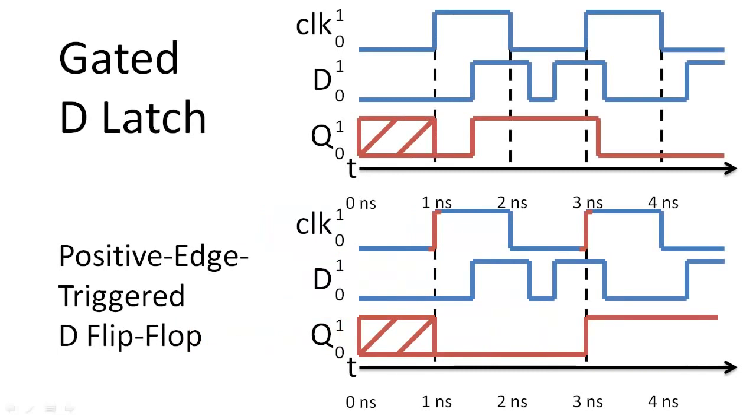Let's recap. We created a sequential circuit called a D latch or D flip-flop. The D latch or flip-flop stores the value of the data input only when the clocking scheme permits the component to read the data input. Different clocking schemes will store the data differently, so we need to carefully choose our clocking scheme and how we send data to these synchronized sequential circuits.